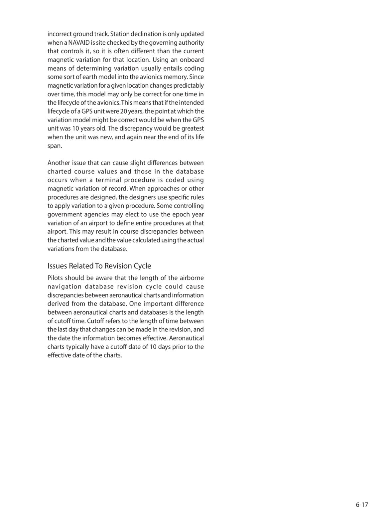Issues related to revision cycle. Pilots should be aware that the length of the airborne navigation database revision cycle could cause discrepancies between aeronautical charts and information derived from the database. One important difference between aeronautical charts and databases is the length of cutoff time. Cutoff refers to the length of time between the last day that changes can be made in the revision, and the date the information becomes effective. Aeronautical charts typically have a cutoff date of 10 days prior to the effective date of the charts.